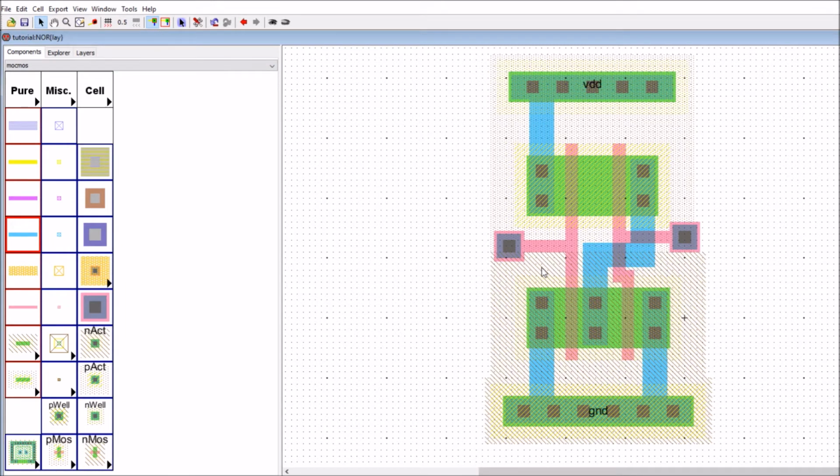So what we want to do now is get access to the two inputs and the output, but not in this layer 1 for the metal. What we're going to do is get the access one layer above. So the bottom layer will be the local connection in between the transistors. The next layer up will be the routing between the blocks or the transistors. So let's say we want to now go from metal 1 up to metal 2. So this is the metal 1 to metal 2 contact, this one here.